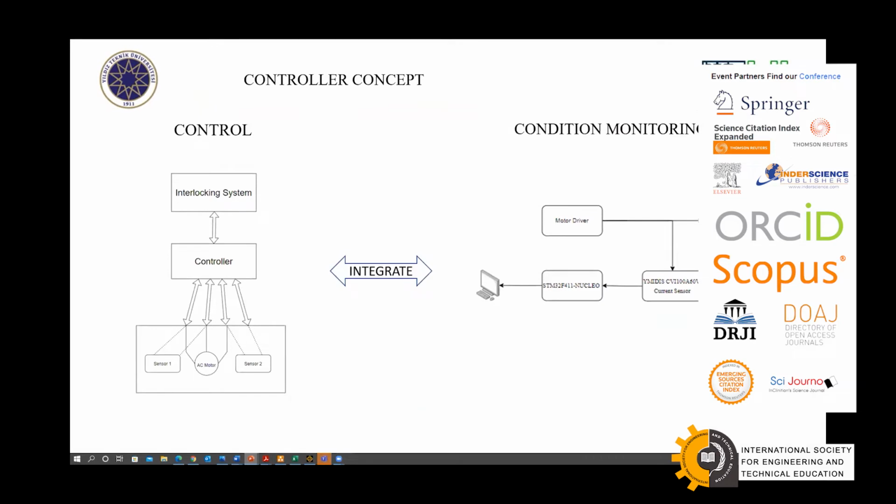In this study, the purpose and concept is to integrate the safety and non-safety system in the control circuit. The purpose is to switch and supervise the point with 4-wire with a control circuit, which is a 1 out of 2 architecture. For condition monitoring, the purpose is using the current and voltage sensors integrated to the control circuit. Collected current and voltage data and additional diagnostic info should be evaluated in regular MCUs.